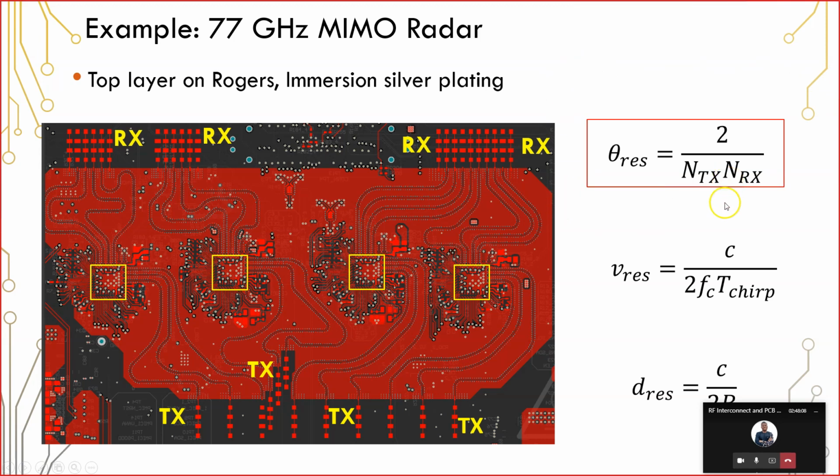The other thing that you can do is you can use that very high resolution for depth sensing and velocity sensing along with a visual image. So like a photograph, something captured with a camera. And that would then take the place of a LiDAR system. So using a camera system along with MIMO radar allows you to build a velocity and distance resolution map that then tracks a large number of objects in a scene.